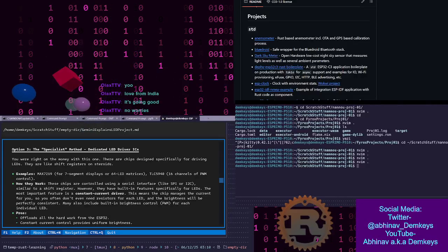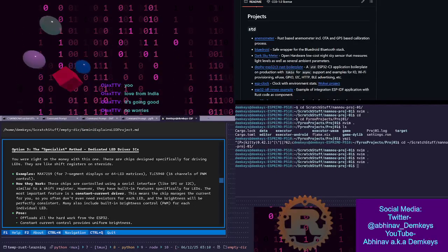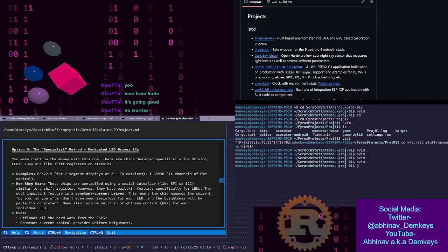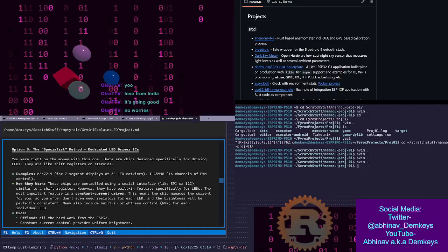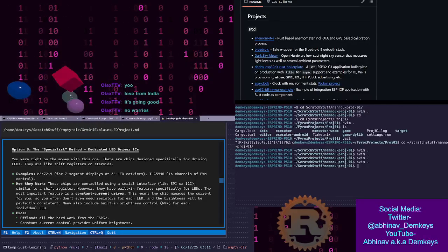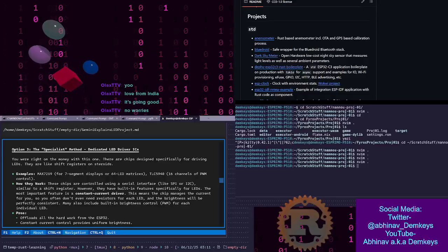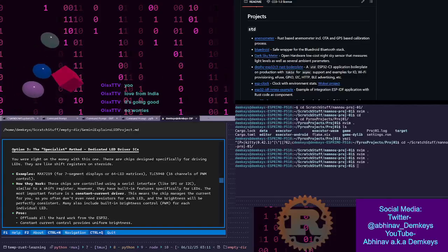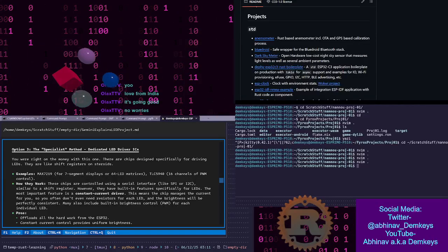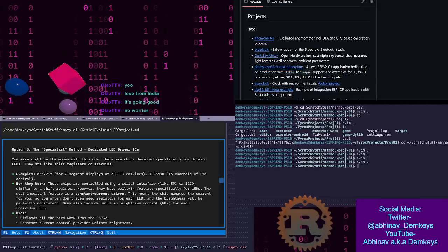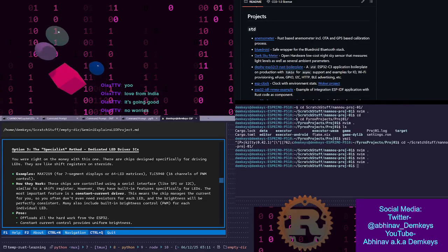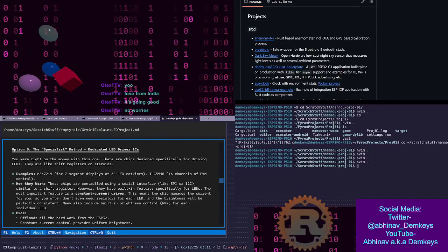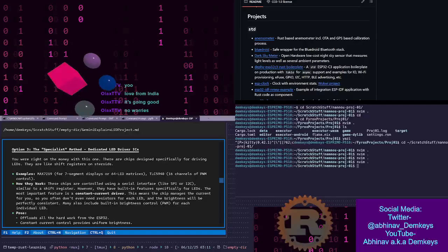So the circuit that I'm talking about is an RGB LED strip, one of those ready-made ones that you get with a remote control with a couple of preset colors and preset modes. You hit a specific button, and then there's an LED driver IC that controls the entire LED strip. The entire strip is RGB lights, so it sends different combinations of voltages to each of the RGB pins to control the color.